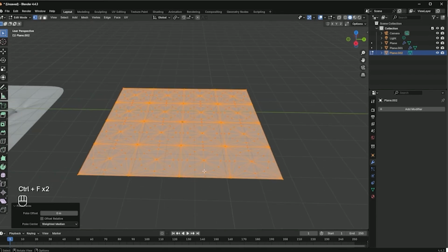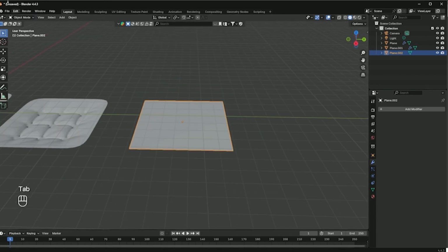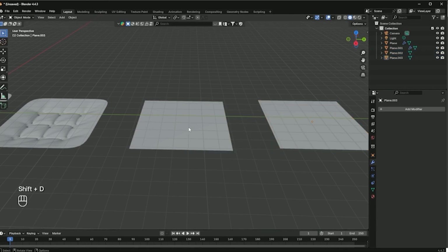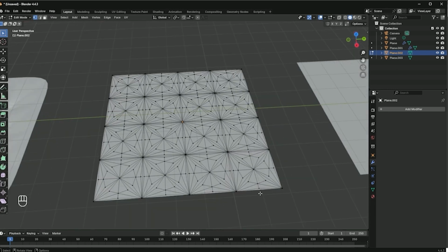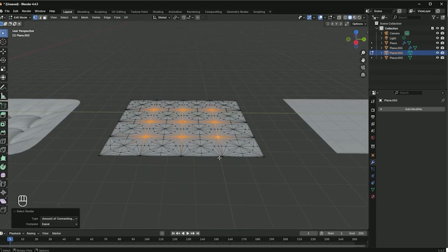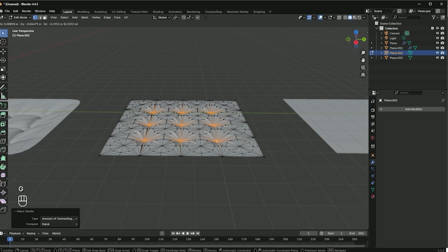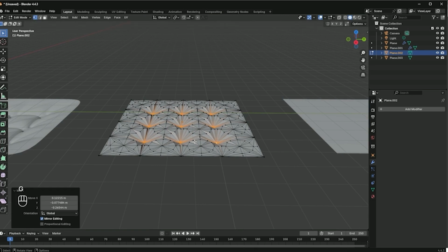Okay, that's 3 times. I press Tab to go into object mode and make a copy of it with Shift+D. Alright, I come back to this part again. First I select this specific vertex, then I press Shift+G and choose this particular option from the menu. Next, I press G and carefully move it further inward. Finally, I press Ctrl+Shift+B to make it significantly bigger and more prominent.